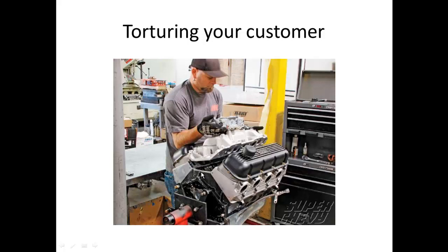The aluminum, being different than the cast iron, would expand at a much different rate, and the cast iron heads would float up and down and away from the aluminum intake, creating a gap, sort of like what he's showing here. And this design flaw caused intake manifold leaks in the Cadillac.